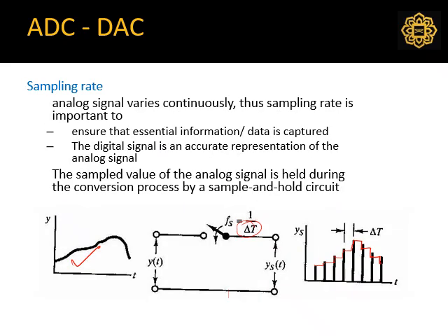Sampling rate. Now, this is very important. Always remember, a pure analog signal is continuous, but a digital signal will never be continuous. It will be like a staircase type of signal. So you do the sample, this is the sampling rate, and you hold. This is called the hold circuit. You hold this value until the next sample, so you will have this staircase type of scenario.